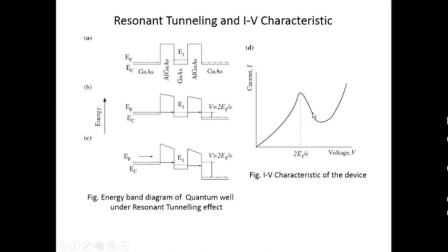So this is the IV characteristic region where the negative differential resistance region comes, or the slope of the IV characteristic becomes negative. Now this continues till a voltage VV is applied on the quantum well, and this voltage VV is the value of the current, which is the valley current. So the current reaches a valley current IV at a voltage VV applied across the junction.